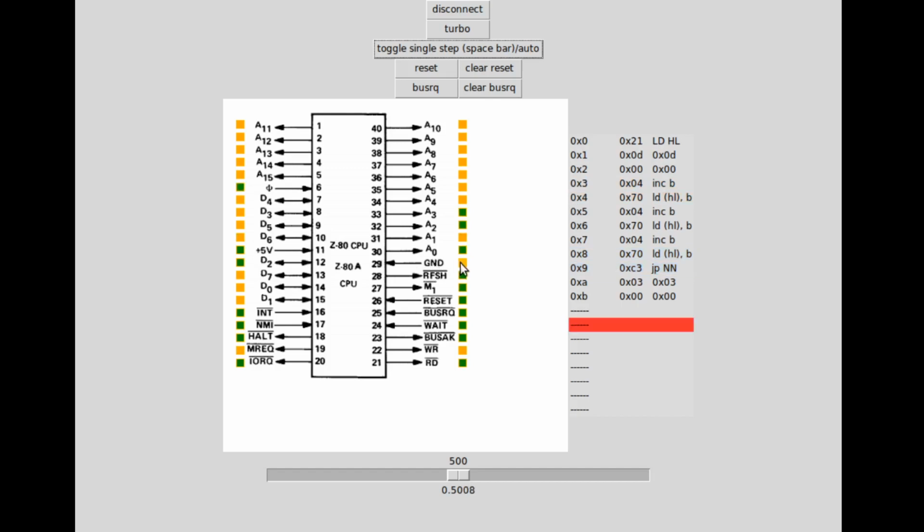So yellow is 0 volts, green is 5 volts. The pins have got arrows on them showing the direction, either outputs or bidirectional for the data ports. Input for the clock here. So the clock's the only pin I'm controlling kind of directly. The chip is reading from memory, so I guess I'm controlling the input of the memory as well when it reads from memory.